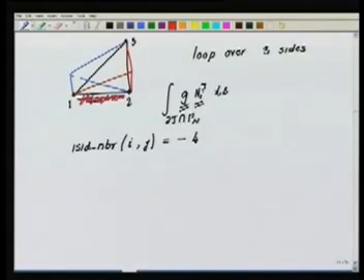Now if you look at these shape functions on this edge, they are exactly the one-dimensional shape functions that we have studied earlier. Why? Because along this edge, it is a line now. Along this edge, your n1 tau is 1 at the first node, 0 at the second node. n2 tau is 1 at the second node, 0 at the first node. So they are exactly the 1D shape functions. So we can use all that we have learned with respect to the 1D integrations to do the integrations of the non-zero Neumann conditions against the shape functions on this edge. Okay, numerical integration, all those things we can do.